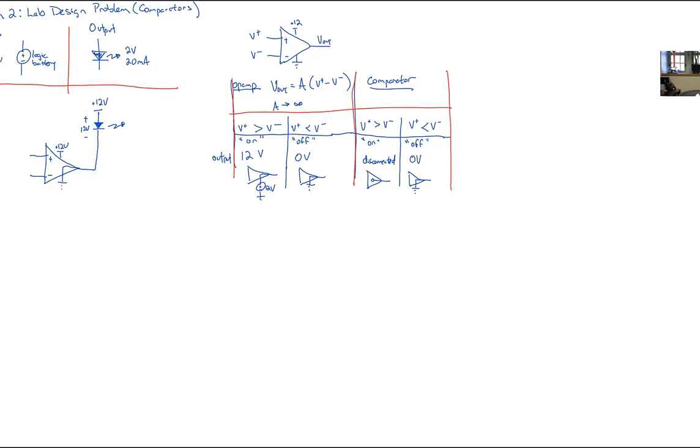But the LED is only rated for 2 volts across it, so it'll immediately burn up the LED and it won't work. So we're going to have to do something to control the amount of voltage across it and the amount of current through it. And to do that, we'll stick in a resistor. You can put the resistor in either side, before the diode, or after the diode. I'll do it afterwards. And to figure out how big a resistance we need, we can use Ohm's law.